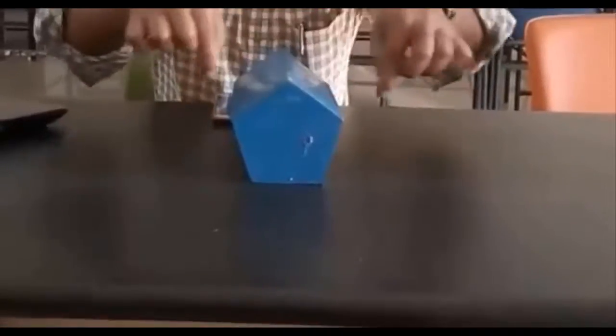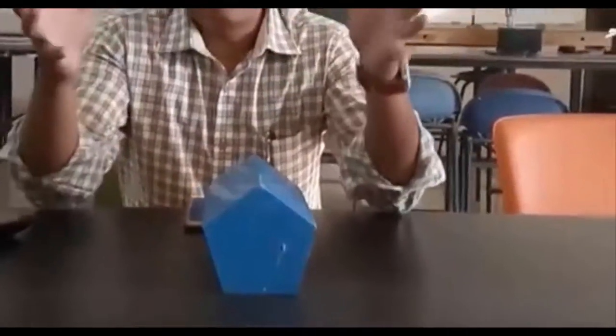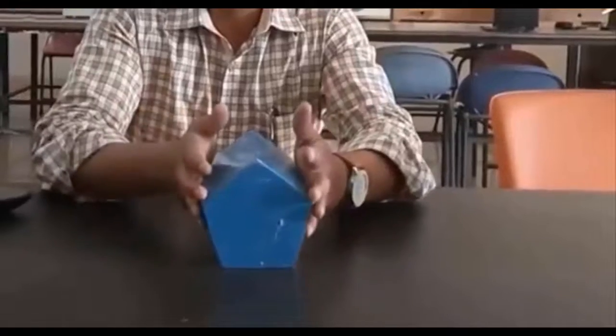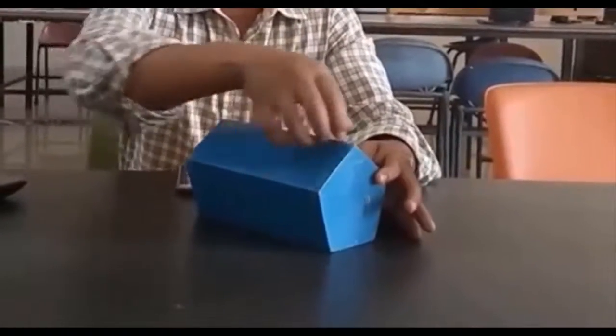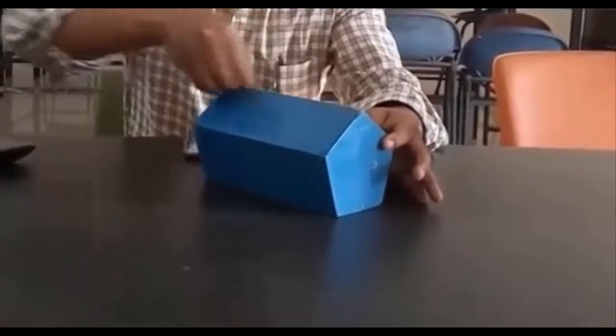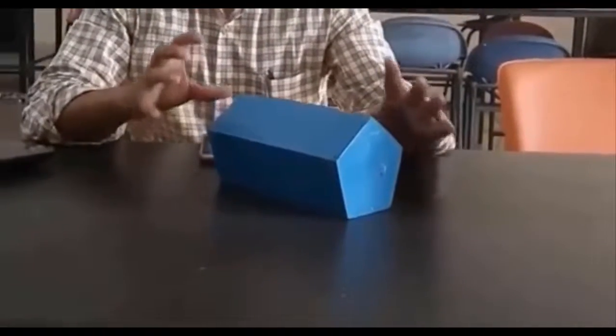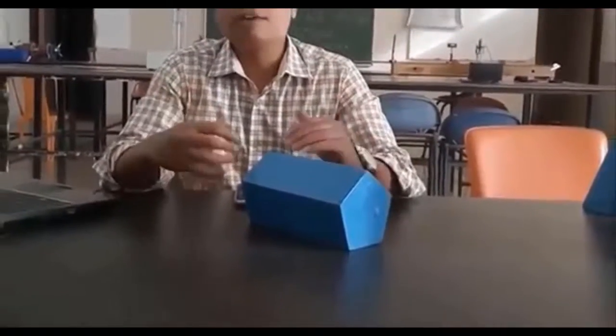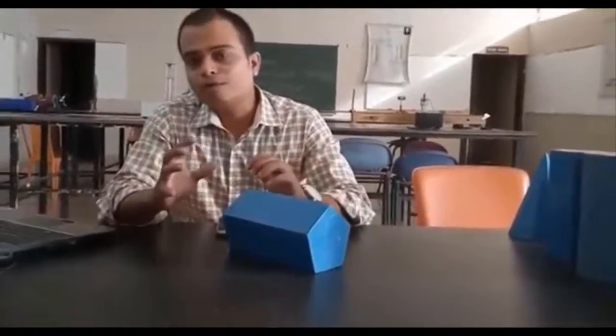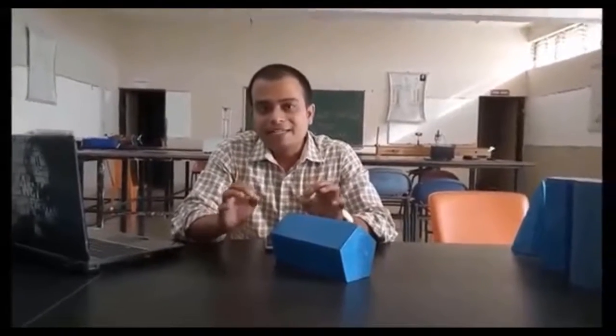So this is going to be the top view, some kind of a rectangle. Step number 2 is going to be by inclining this. We've got to ensure that this particular prism makes a certain angle with the vertical plane. That angle is 45 degrees. So this is going to be our step number 2, where we are going to modify the top view of step number 1 by tilting or inclining it at an angle of 45 degrees, and accordingly we are going to draw the final front view in step number 2. So that's exactly what we will be doing.